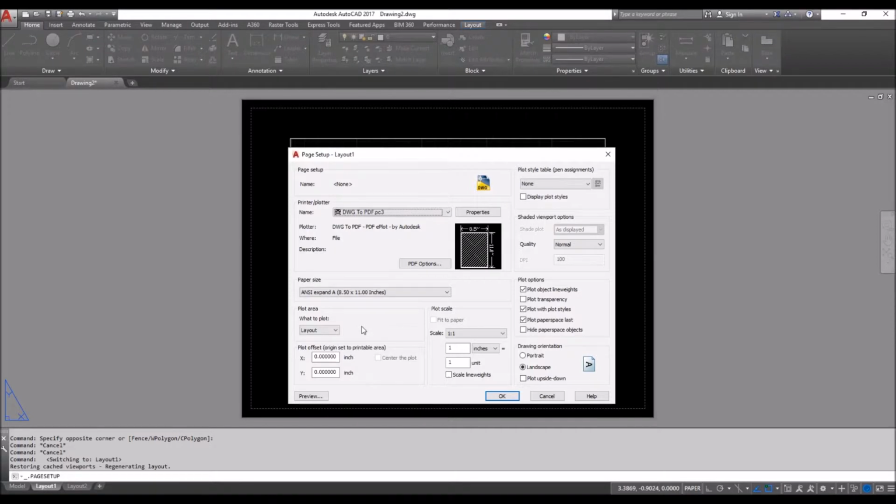With that option, if this file is sent to some other office, or if it is opened within the office on different computers and you're plotting that sheet, it will eliminate the problem where it says that the plotter is not found or that the page setup is not found. The second point is that, at least in my habit, every time I print anything, I will see a PDF of it first, zoom in, zoom out, or see how it looks digitally. The second part to it is whenever I have to send a file, this forces me to save it in a location in our out folder.